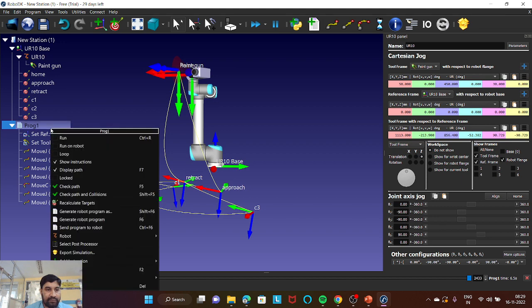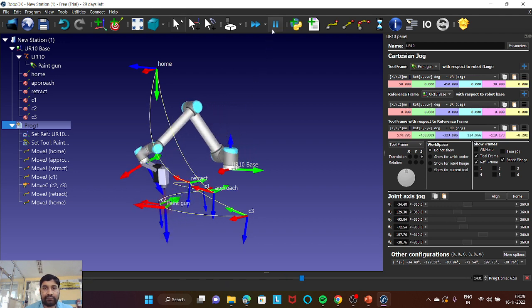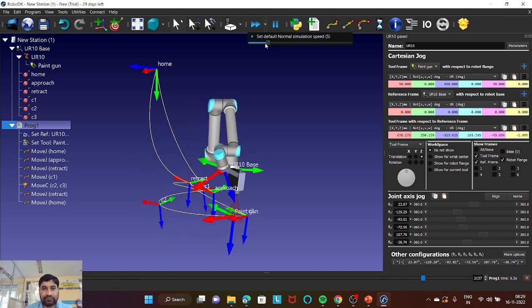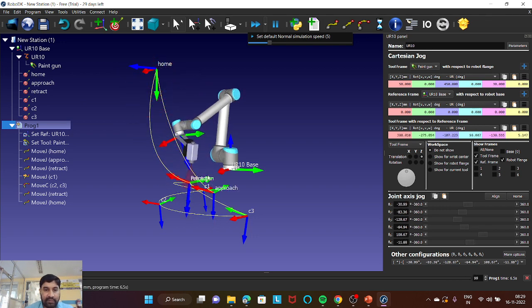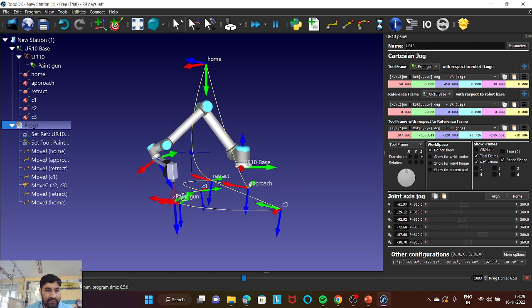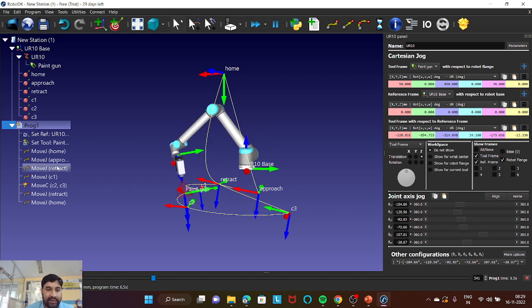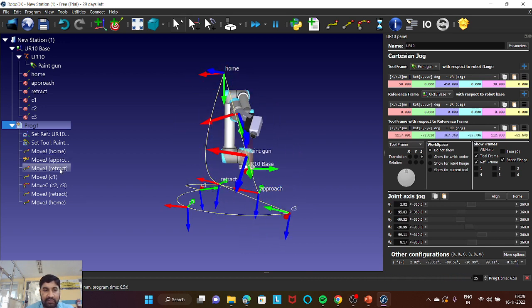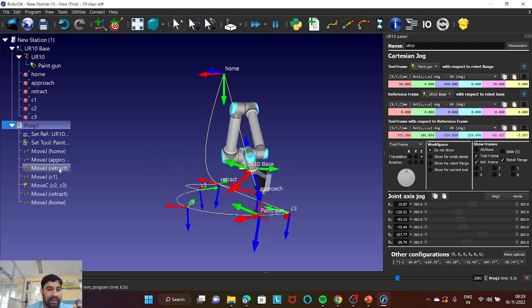So I'll give loop here. I'll do it a bit slowly to explain my targets. Okay, this is my home position. Home, it has come to approach from... So something wrong happened here. What is that? From approach I have moved to retract, so that is not required here. Retract should come only after finishing my target, when it comes back to the retract here.